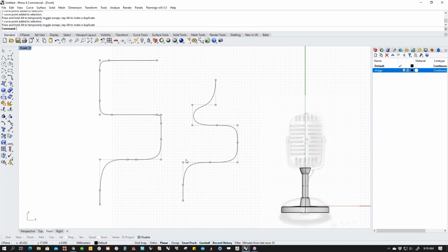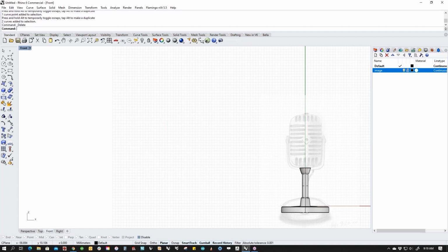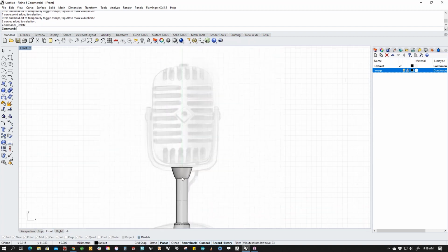But my point of all of this is reduce the number of points in your curves. Fewer points, pull them farther, make them work harder. If you make a corner, it's only 3 points. Don't do more, all right? That right there is going to help improve your surface quality a lot. So that said, let's start from here.